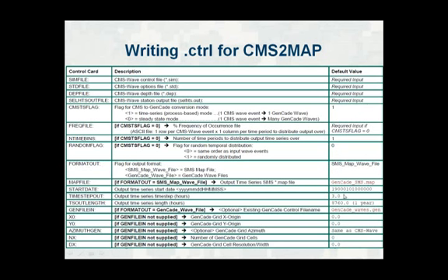You have your start date, your time step out in hours, and your length of simulation, which is in this case a year. If you have an existing Gencade file, this is your name. If not, and you still want a .gen file, you can insert an origin, the azimuth, and your incremental, like the number of grid cells and the size of each grid cell. And I'll show you an example of the control file in a minute.